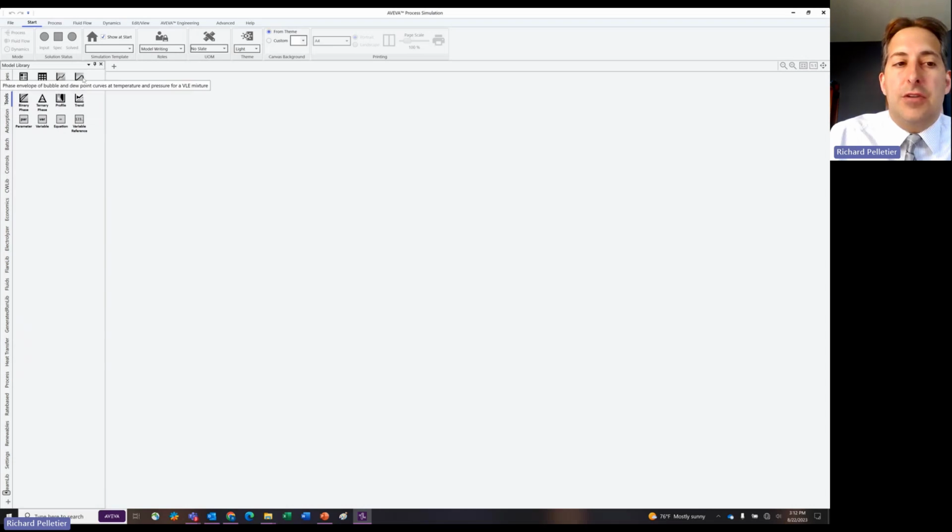And you can also do phase envelopes. So you have these capabilities that can link back to the fluid without actually having to use the fluid in a source model. You can just pull these and connect them to the fluid, set the conditions that you want to evaluate, and they'll spit back different results depending on the type of plot or capability that you're using.